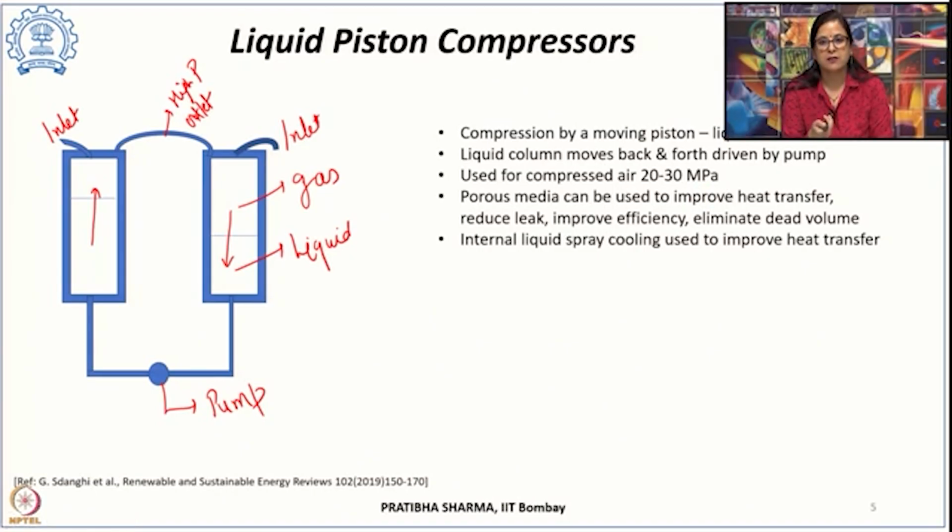Now, there is very good heat transfer involved, because whatever heat of compression is produced is absorbed by the liquid and this can be cooled down. So, this operates under isothermal conditions, but we can further improve the heat transfer characteristics by including a porous media. This porous media will have several interconnected pores in which the liquid can flow, and that can provide a high surface area, and that will result in better heat transfer.